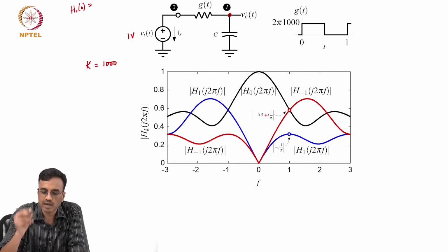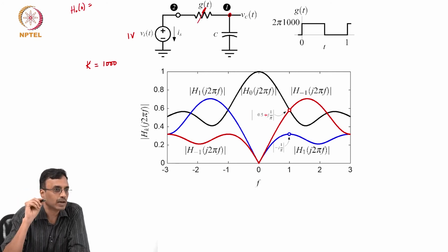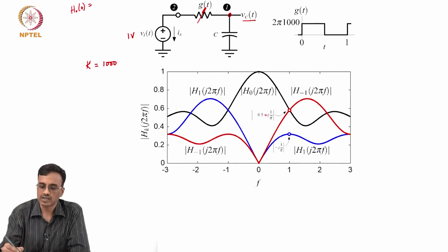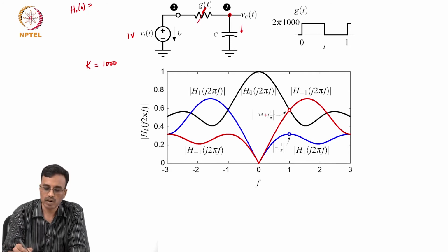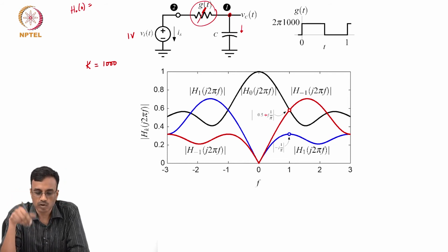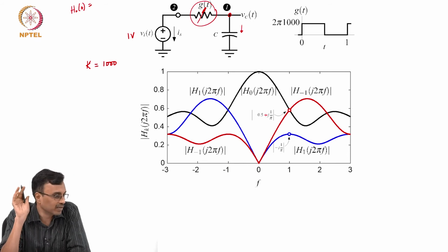So if you put in DC here and this resistor is changing periodically, what comment can you make about this waveform? It will be constant, right? Because if it's constant, there's no current flowing through here. If there's no current flowing through here, there's no voltage drop across the resistance. So basically, one way or the other, you've solved, within quotes, Kirchhoff's voltage law and current law, right?